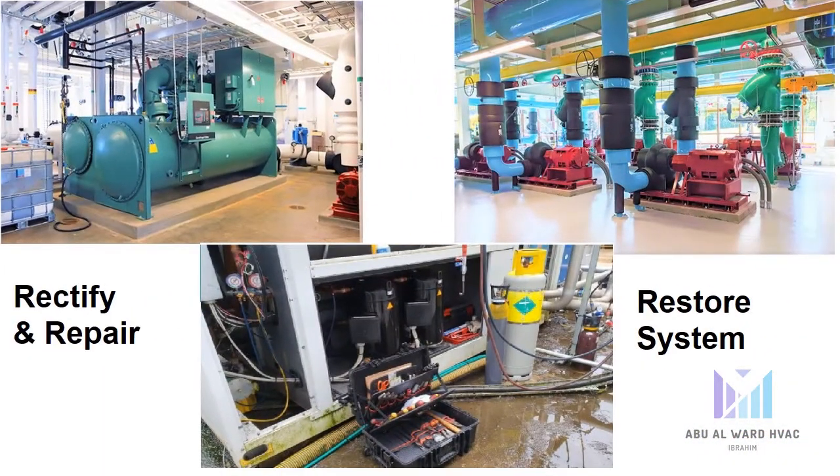Second, corrective maintenance. Corrective maintenance is inherently part of emergency maintenance because when there is an emergency, something needs to be corrected or fixed. In this way, corrective maintenance is mostly reactive. However, it can also be proactive. If an asset with a condition monitoring sensor detects an issue, a work order is created and a technician is sent to correct it.